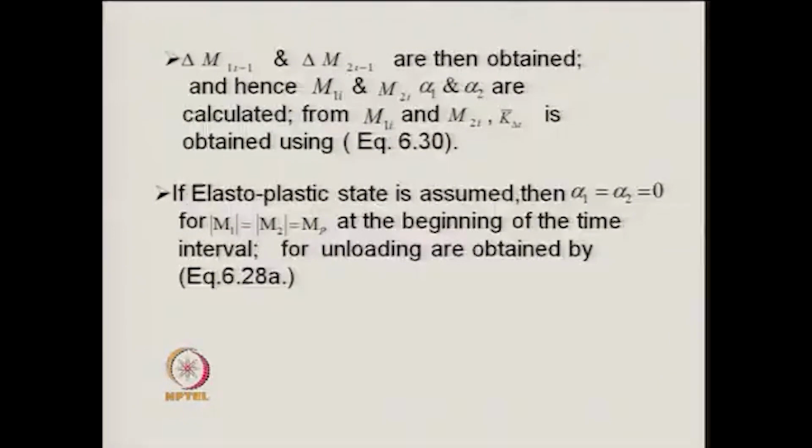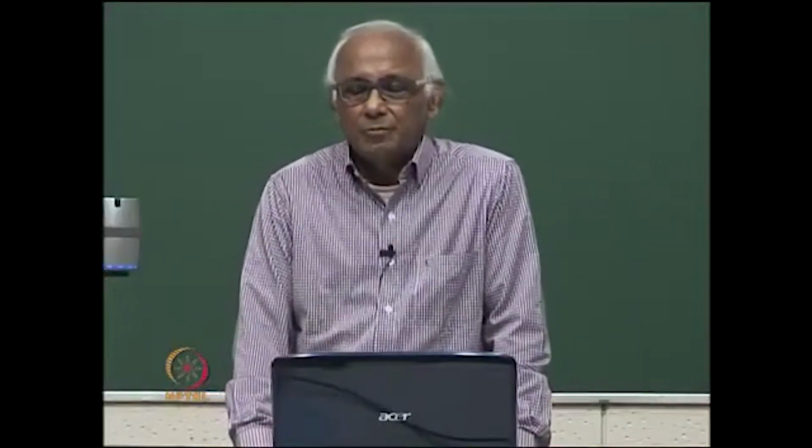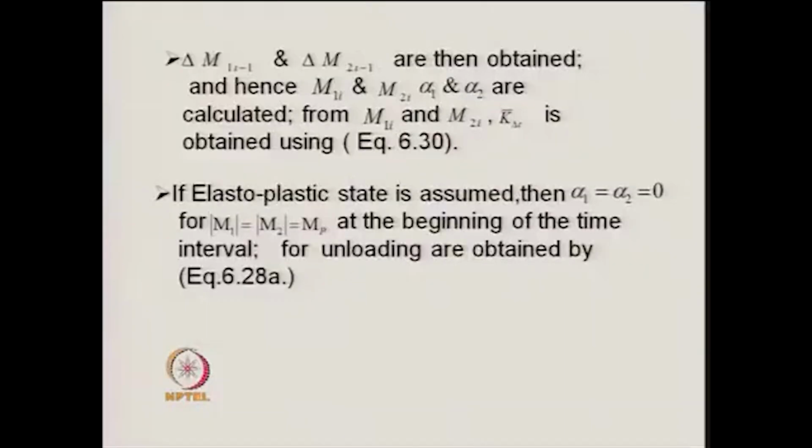So, in this particular way, one can find out the total stiffness of the system at any increment of time delta t, and with the help of that stiffness we calculate the incremental displacement, that is displacements and rotations for the system for the incremental loading.